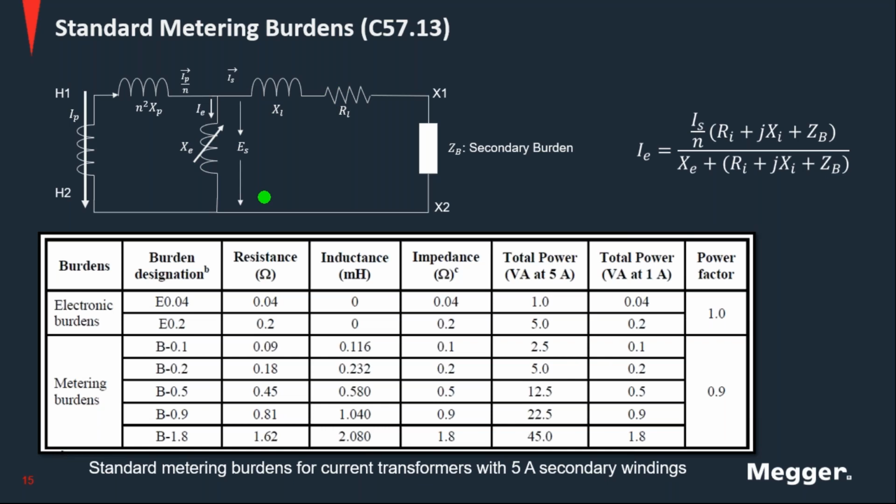This is the CT or the VT, we can have the same thing for a voltage transformer, but this will produce a voltage or a current at these terminals, and now this burden cannot exceed certain limits, because if not, it is not going to perform as specified. So that's what we also have from the standard. We need to guarantee that the burden connected to this instrument transformer is not exceeding these limits.